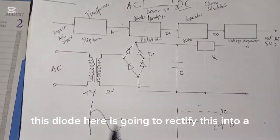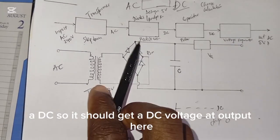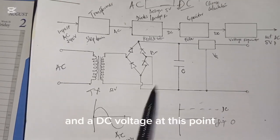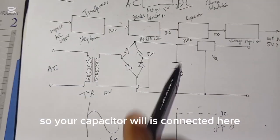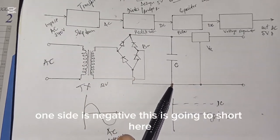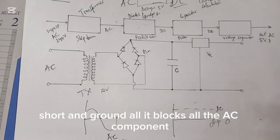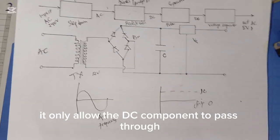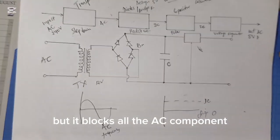This diode here is going to rectify this into a DC. So we will get a DC voltage at the output here and a DC voltage at this point. Then it will be fed to a capacitor. So a capacitor is connected here. This capacitor is connected in parallel. One side is positive, one side is negative. This is going to short to ground, or it blocks all the AC components. It only allows the DC components to pass through, but it blocks all the AC components.